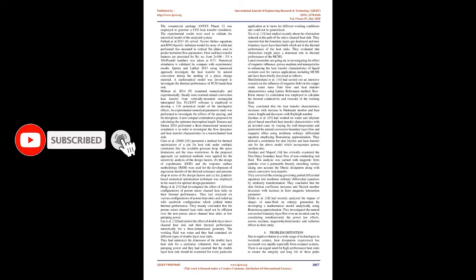Dongquan Kim et al. 2009. 4. Compared the thermal performances of 2 types of heat sinks, i.e., plate fin and pin fin. Their investigation results propose a volume averaging approach-based model for envisaging the pressure drop and the thermal resistance. Burek and Hoffit 2009. 5. Developed an expression for prediction of the optimal fin spacing for vertical rectangular fins with rectangular base. The correlation was predicted on the basis of experimental data.